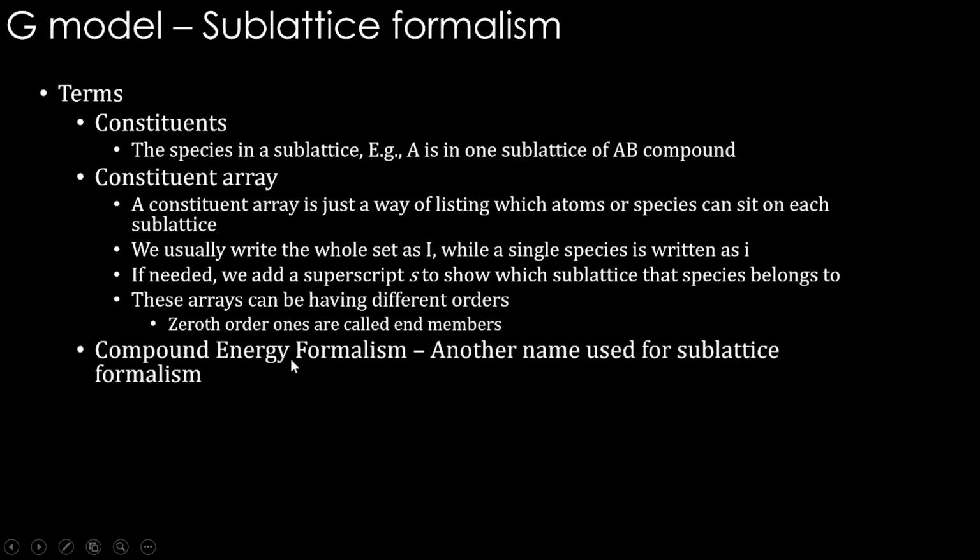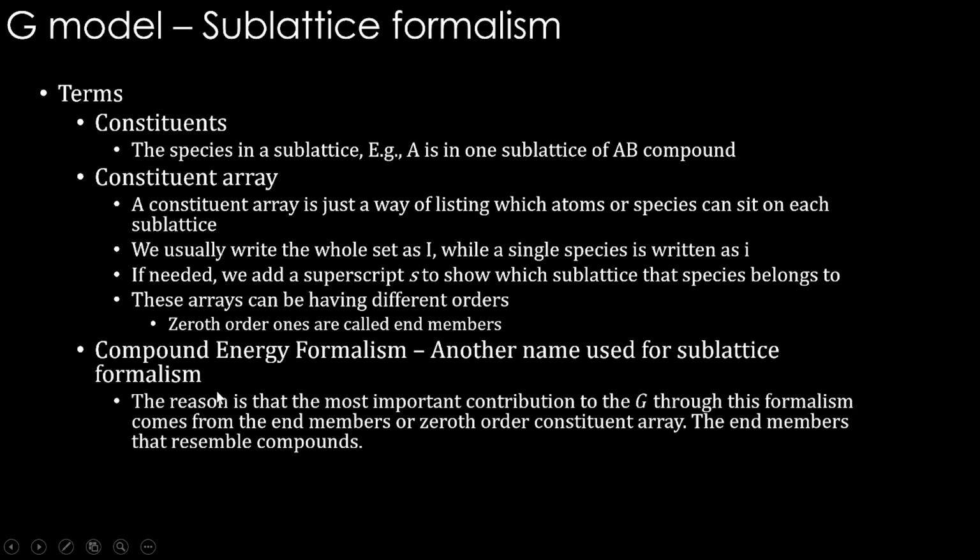And the term compound energy formalism is another name used for sublattice formalism. The reason is that the most important contribution to the Gibbs energy through this formalism comes from the end members, or the zeroth order constituent array. Okay, the end members that resemble compounds. That's the reason why we are using the term compound energy formalism.